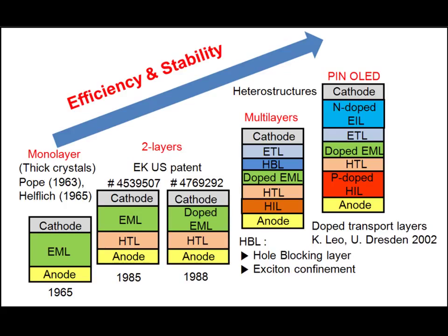Although the bilayer OLED is the most widely fabricated configuration, there are different variations of the OLED with varying layers. When the OLED was first tested in 1965, there was only a single emissive layer between the cathode and the anode. From there, a hole transport layer was added right on top of the anode, and the emitter also doubled as an electron transport layer, which would later be separated into two distinct layers. In further attempts to increase the efficiency in radiative recombination, a hole blocking layer was added to try and increase the recombination rate in the emissive layer. These heterojunction OLEDs are the latest attempts in making OLEDs as efficient as possible.